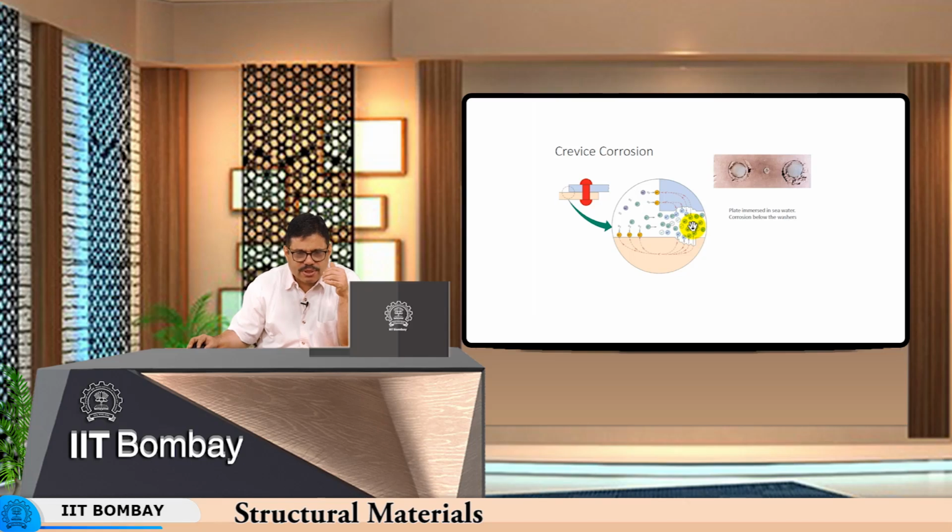So, more and more of these chloride ions can go further in and ionize the metal. The result of ionization is that the electrons which are given out travel through the metal and come here and form OH minus ions. So, this is what happens over a period of time when a plate is immersed in seawater where sodium and chloride is present together with oxygen. Sodium chloride dissolved in water is bad enough, but then oxygen makes it even worse.